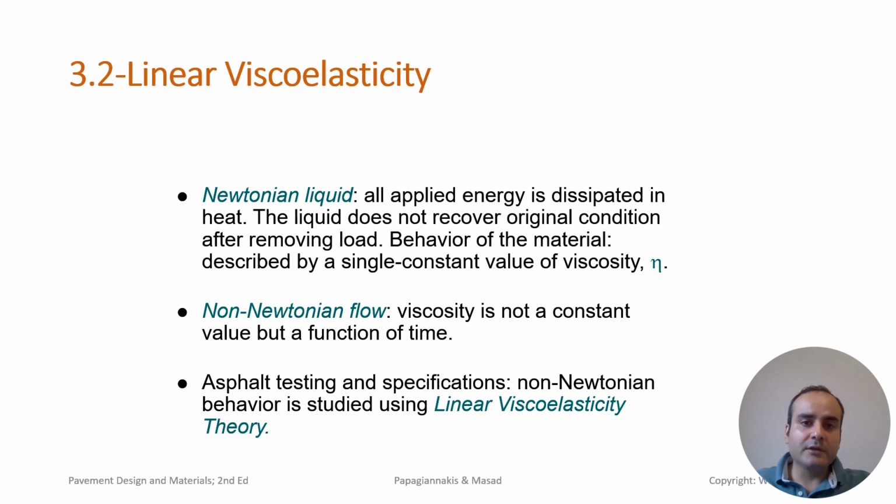In a Newtonian liquid, all applied energy is dissipated in the form of heat. The liquid does not recover its original condition after removing the load. The behavior of the material is described by a single constant value of viscosity. In non-Newtonian flow, viscosity is not a constant value but a function of time. The non-Newtonian behavior of asphalt binder is studied using linear viscoelasticity theory.